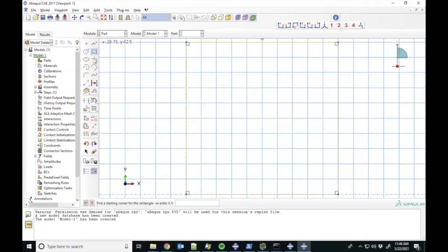And then in this lower left corner, we're going to draw a circle centered at the origin. So we click for the center at the origin, click somewhere along this bottom line to choose the radius of that circle. And then we're going to use the dimensioning tool to write that the dimension of this circle's radius is 3 millimeters.